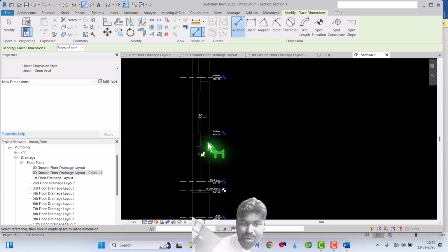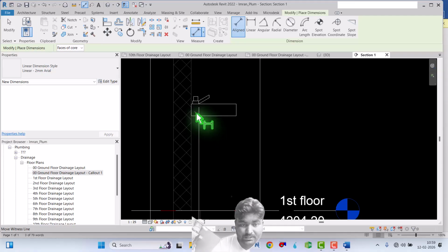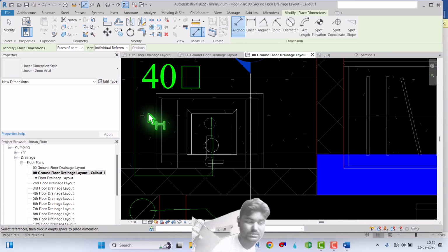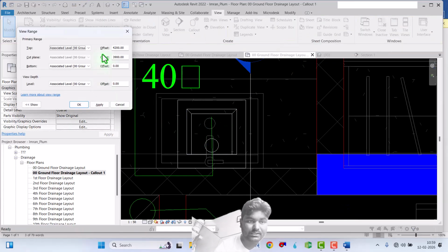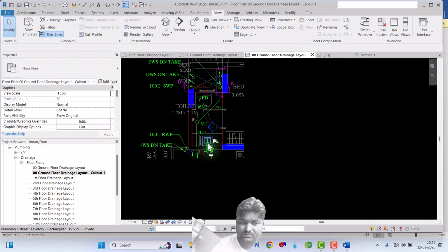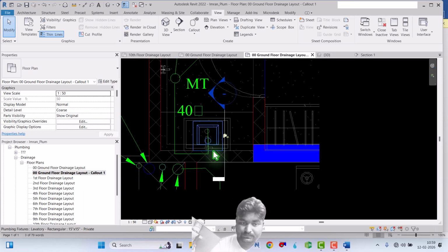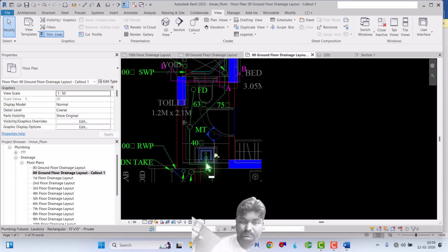Okay, from here, so above this one I have to cut to see our wash basin. This is the reason here I cut on 3900, that's why it is now visible. Okay, so you can set as per your need. So now it is visible.